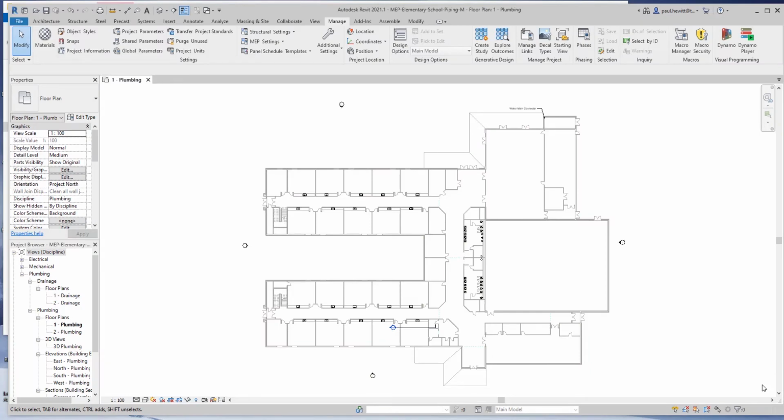In this exercise, we're going to draw cold water mains from the origin point to the classroom wing, changing the diameter and the offset to the pipes as we draw them. We'll then connect the water heaters to the mains and then draw hot water pipes from those water heaters to the classroom wing. Finally, we'll draw sloped sanitary piping from the floor drains.